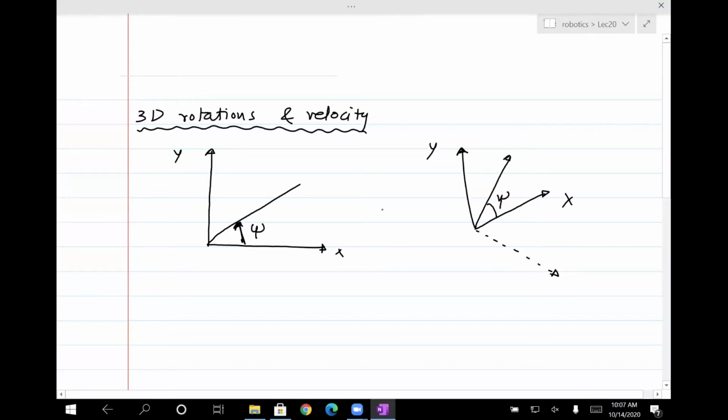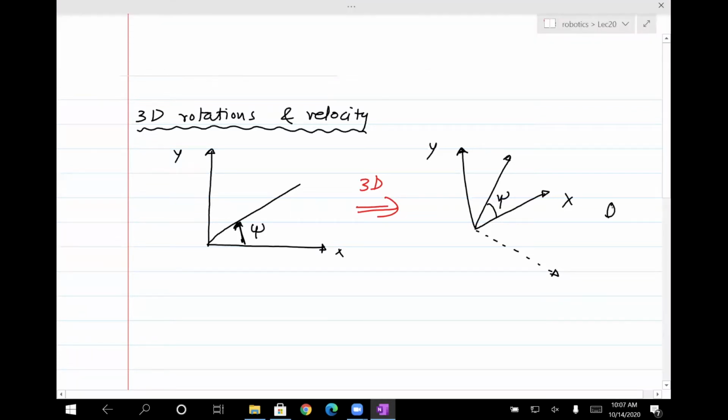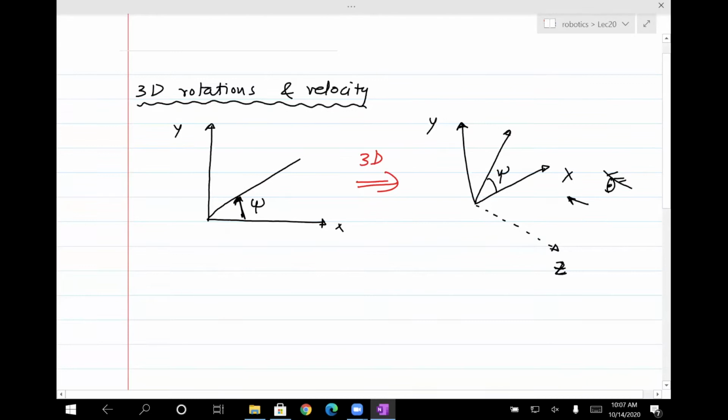So this is the 3D view of the same thing. Okay, and you are looking at it this way. Since you're looking at it this way, you don't quite see the z-axis, but the z-axis is still there. Okay, so what we did was we wrote the rotation matrix as, so we wrote frames, and then this is x1. Okay, I will not show the y1 and so on, but this is what we wrote: cosine of psi, minus sine of psi, sine of psi, cosine of psi, right?